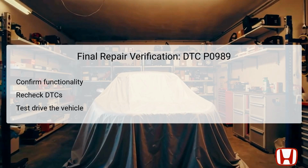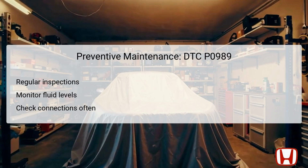Pay attention to the vehicle's shifting capabilities across all gears, particularly ensuring movement through the 1st to 6th gears is smooth and responsive. A passing verification ensures that the issue was effectively addressed and the vehicle is safe for regular use. To avoid encountering DTC P0989 in the future, preventive maintenance plays a key role in sustaining the health of the transmission system. Regular inspections of the wiring and connectors related to the transmission fluid pressure switch can help identify issues before they become problematic.